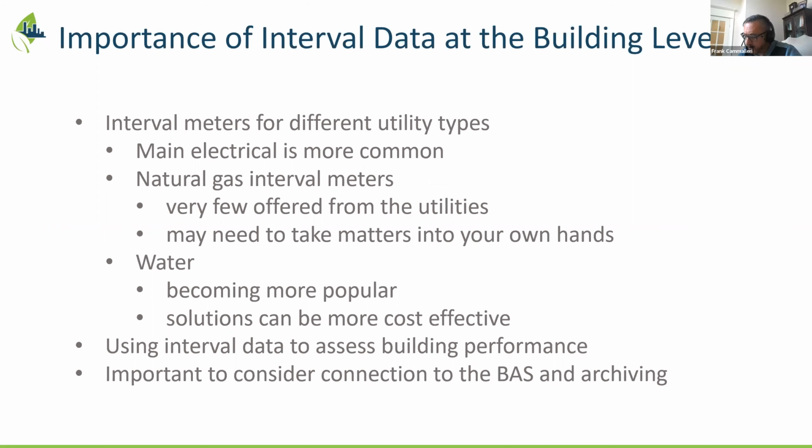Oh, okay, great. Was that a typical cost you might have had for something like that? Was that in the 3 to 6K range? Yeah, somewhere between 3 to 6,000 should be for either an insertion or a redundant inline meter. Again, you'd go insertion on larger loads, and you can do an inline redundant meter on smaller loads. Okay, perfect. Thanks for that.